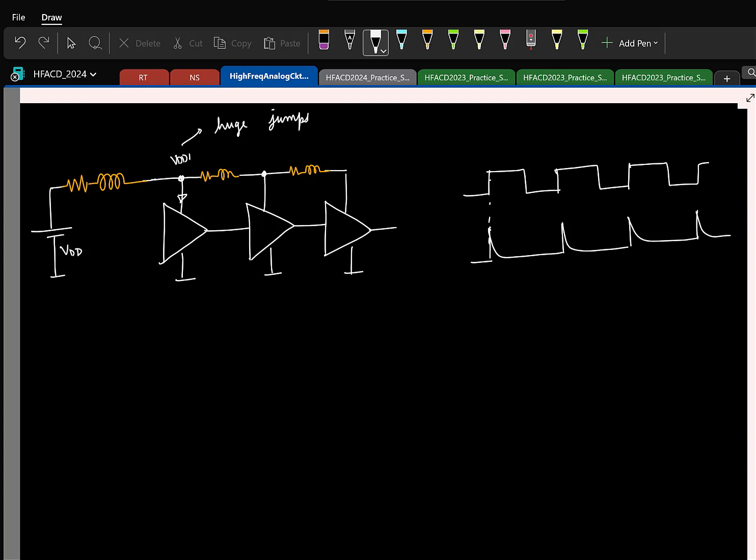Is this good or bad? Yeah, bad, simply because the transistors inside might easily go in and out of saturation, right? That's the simplest thing. So this is something that is not good. So let us see what could be one fix for this. Here, let me draw it here. The issue here is that we have spiky current drawn in this path.